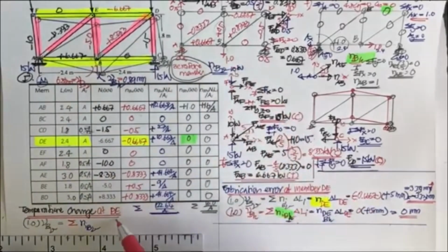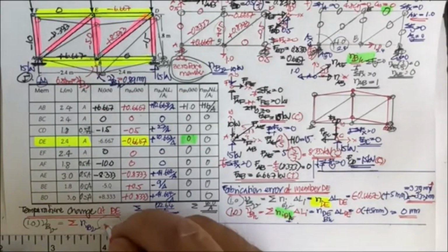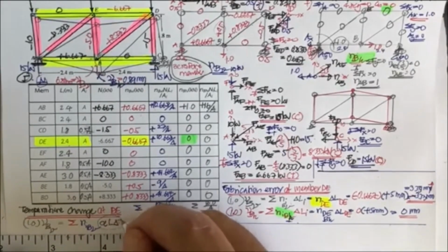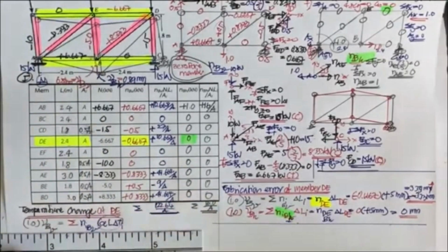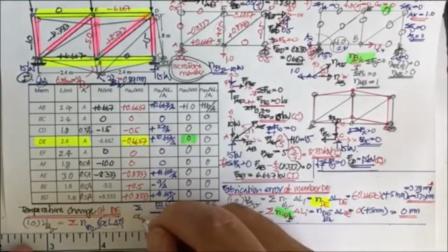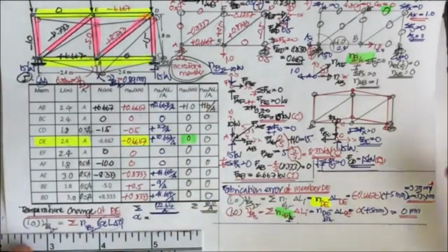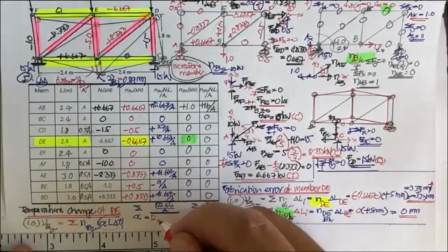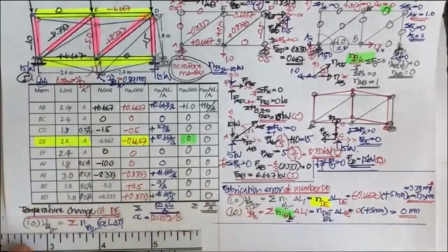The deformation due to the temperature change, and you know that this is going to be alpha L delta T I. That's what we studied is due to the temperature, in which alpha is the coefficient of thermal expansion, and you know that alpha is going to be 12 times 10 to the minus 6 per degree Celsius.